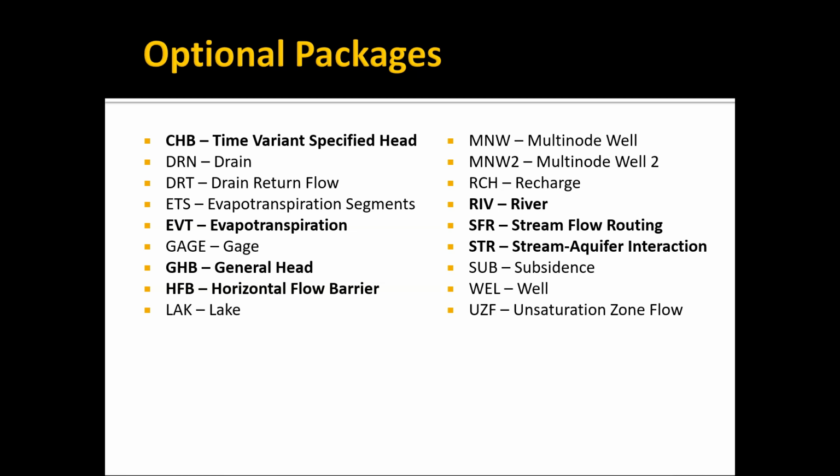The SUB or subsidence package allows you to simulate aquifer subsidence, where if you dewater certain kinds of aquifers, you can end up causing the effective stresses in the aquifer matrix to get too high, and it will cause the aquifer to compress and lose porosity. And you can simulate that with the subsidence package.